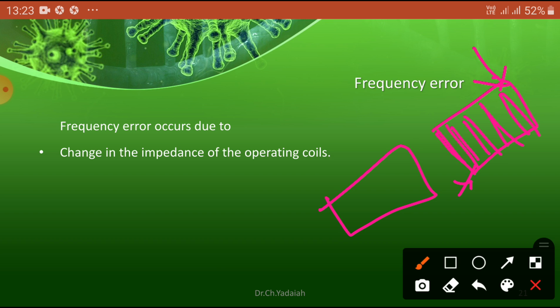Okay, in our DC motors and AC motors, each lamination is 0.35 mm to 0.5 mm thick. In the case of transformer cores, sometimes we use an amorphous core, which is very thin, just like paper thickness, used in amorphous transformers to reduce the eddy current losses.